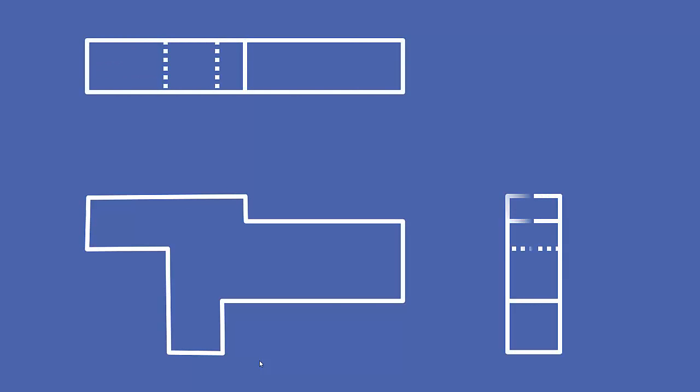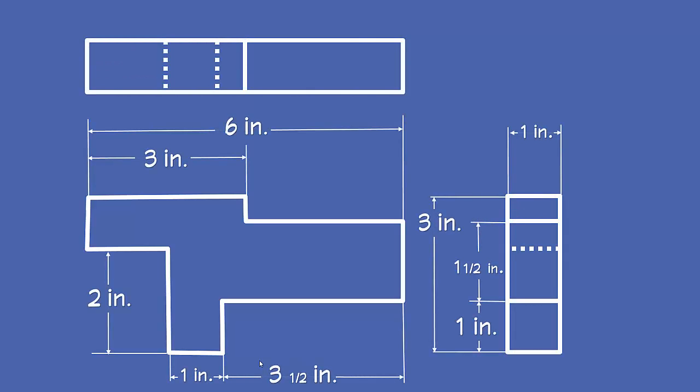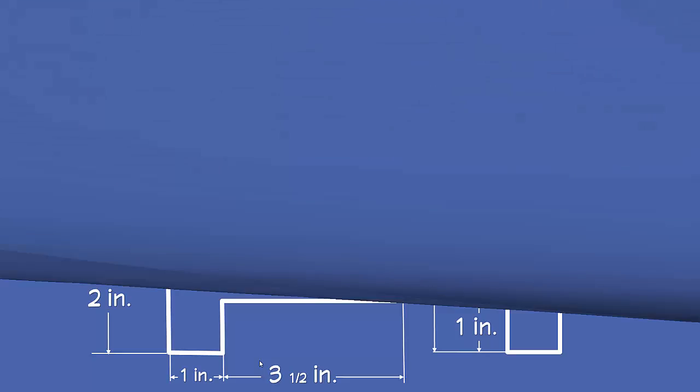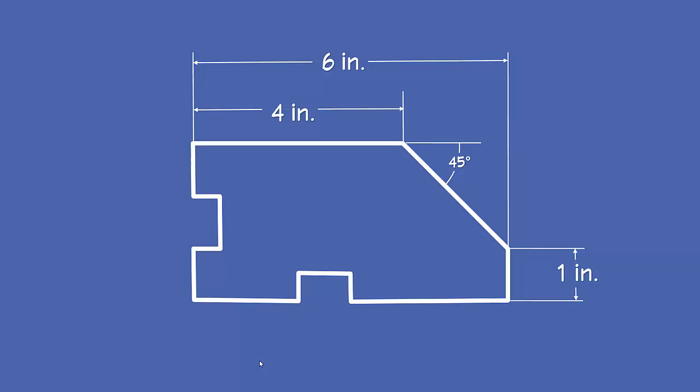You also need to fully dimension your widget. Okay? So when doing your orthographic drawing, you need to remember good solid object lines, thin dimension lines, use arrows, keep your lines straight, make sure you're not missing any dimensions. When dimensioning angles, remember you only have to do angles if you think they're vital and essential. Now, we're more concerned about the dimensioning of the location of each corner than being concerned about the angles or the length of a slope.